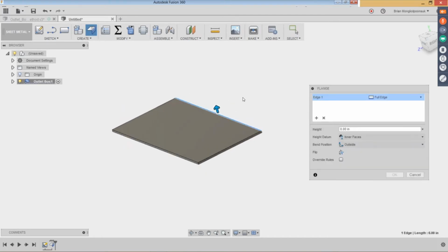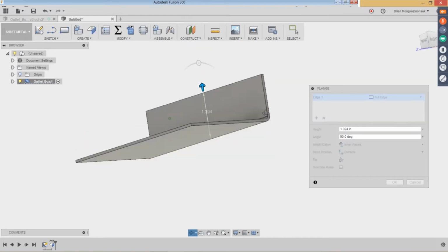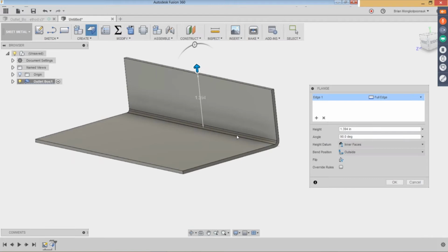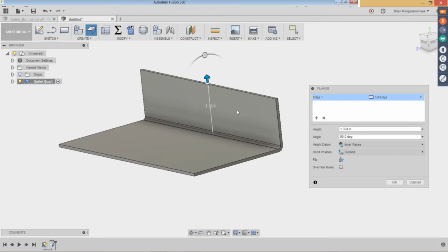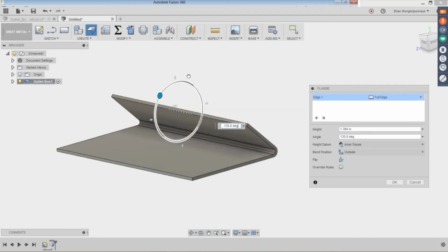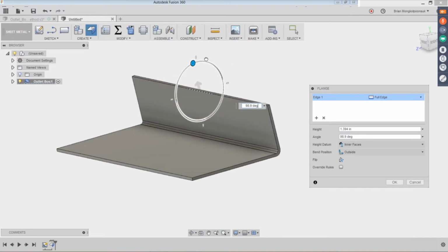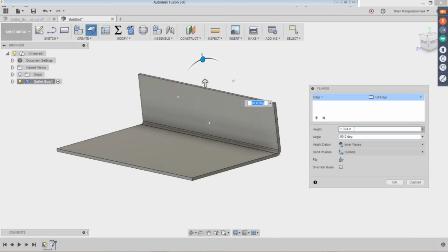The second feature to the flange tool is its ability to create bends. So notice how there's a radius here, and that's once again in respect to the sheet metal rules that was specified in the aluminum inches units that I selected. You can also have the option to bend it forward and backward by using this tool here, or by entering a value. And you have the options for selecting how tall it's going to be.